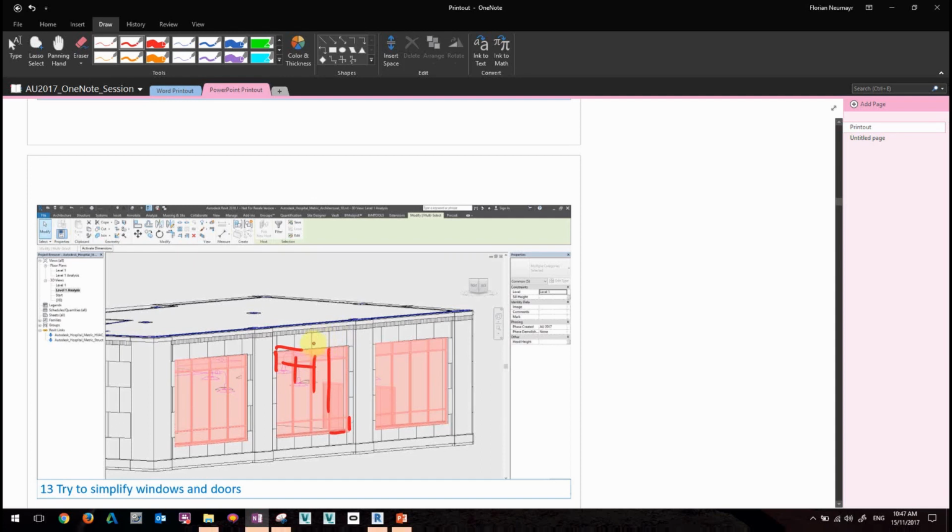because for my CFD analysis to work, I would need to mesh this whole thing. And the more refined my details are, the more refined the mesh needs to be. If I have a whole building, and you probably know that the smallest thing you can model in Revit is 1/32 inch, within a project base point with a radius of 10 miles, you don't get a problem.